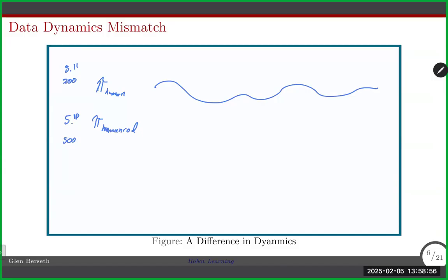It's still tricky. Most of those sensors are not very accurate. So a weight sensor, I believe in this case, would be a form of an IMU, which is detecting the accelerations that go on at the end of the hand or something like that. So IMUs are a nice way to be able to collect some data. They drift really quickly after about a second or two. So after a second or two, they're not very accurate.